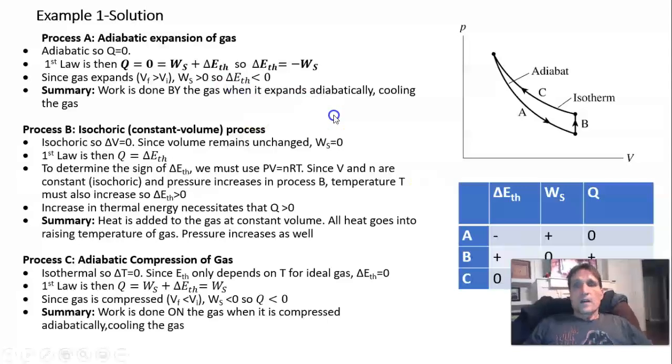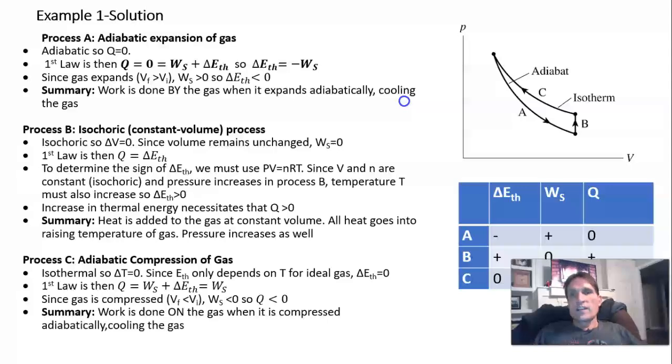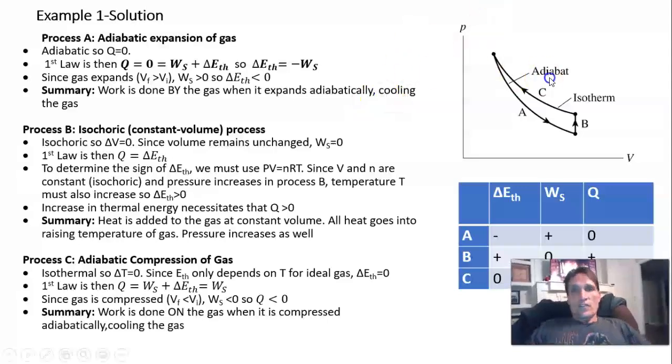So what's this saying in words? It says that when a gas expands without heat being added, meaning adiabatic, it cools. The gas does work in expanding, and that work cools the gas. It comes at the expense of thermal energy. So work done by the gas when it expands adiabatically results in cooling. And this is important for any gas. If a gas expands and heat is not added and work is done by the gas, it will cool. So that's process A.